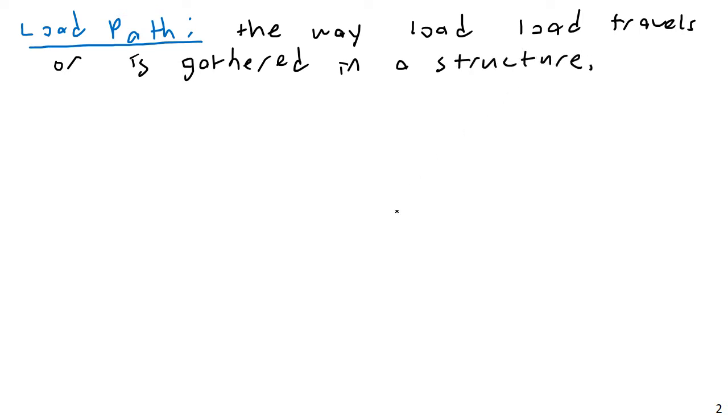Ultimately, at least in a civil engineering application, where do the loads always end up? The reactions. That's true, but in terms of actual physical structures, what do those reactions mean? The foundation, yes. Ultimately, all the loads of a structure end up in the foundation, delivered to the soil. If you're designing airplanes this may be a little different, but for any civil engineering application, the loads must find their way to the soil.